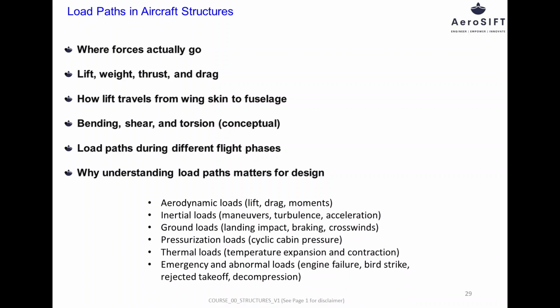Modern aircraft structures are designed to withstand multiple load types, often acting together. Aerodynamic loads: lift, drag, moments. Inertial loads: maneuvers, turbulence, acceleration. Ground loads: landing impact, braking, crosswinds. Pressurization loads: cyclic cabin pressure. Thermal loads: temperature expansion and contraction. Emergency and abnormal loads: engine failure, bird strike, rejected takeoff, decompression.